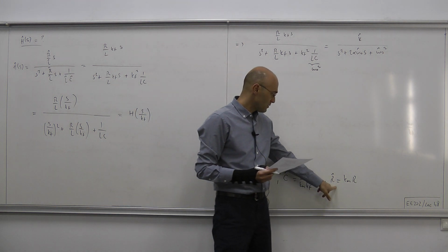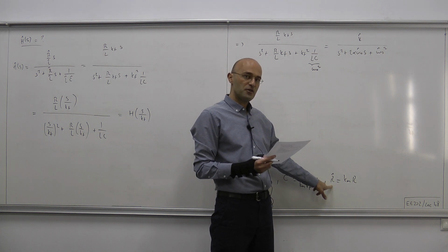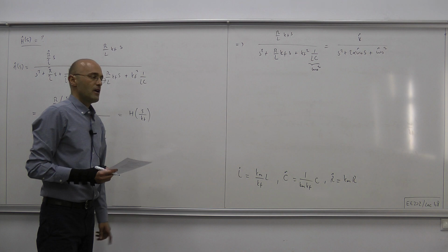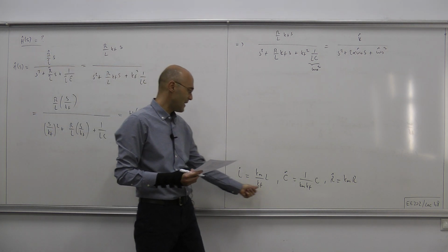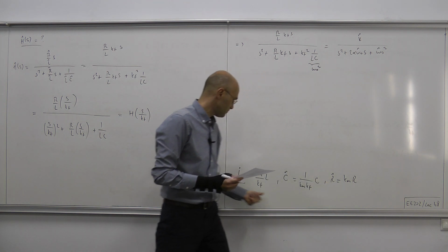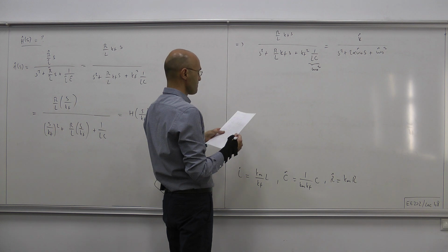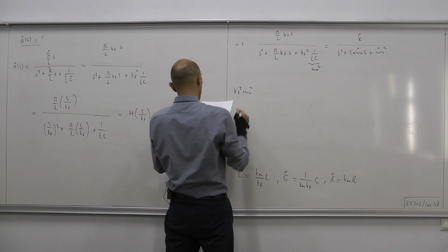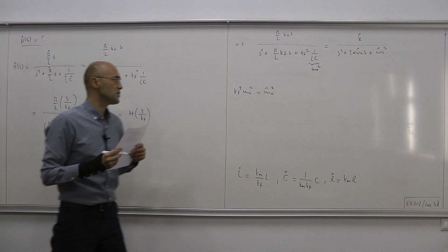And from this relation we have R equals 1 ohm and we have the desired new resistance value. Okay, we can figure out the magnitude scaling factor, and then once we have kf and km we can compute L hat, C hat and R hat through those expressions. So therefore we're done. Basically kf squared omega 0 squared equals the new peak frequency squared.